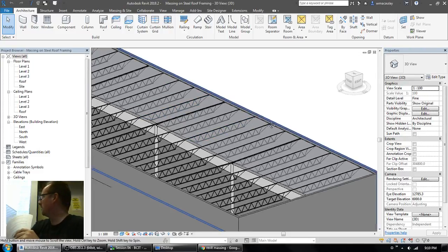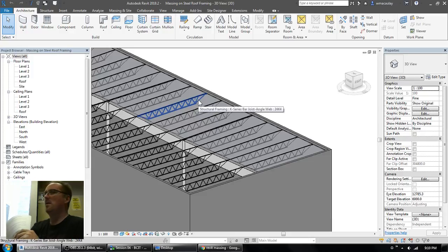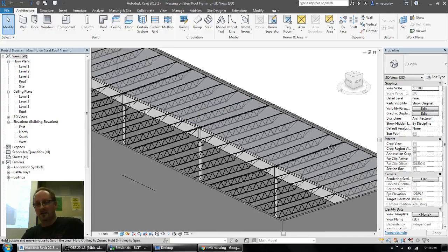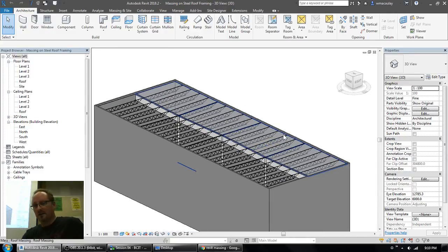Not always, but commonly it's done. Now we don't bother modeling those pockets when we're doing tilt construction. But to get slope to drain, what they do is they typically, and you can see it here on the inside, the structure is sloped so that you have low column, high column, low column, and there'll be a roof drain by the low column to collect rainwater that runs on the roof and is collected at these drains.